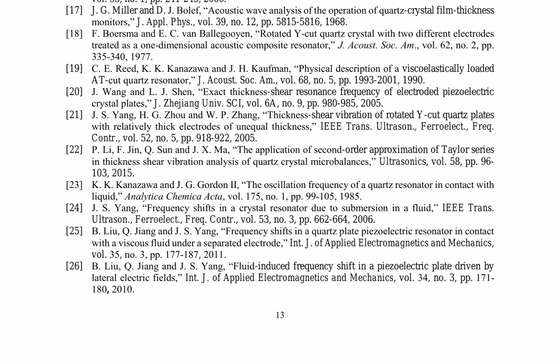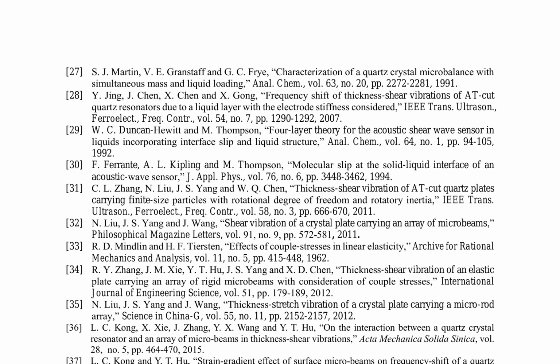It then explores the impact of these loadings on the frequency shifts of the quartz crystal resonators in thickness shear modes. The authors also delve into the effects of couple stresses and strain gradients on the vibrations of the piezoelectric plates, providing detailed mathematical models and equations to describe these phenomena. Furthermore, they examine the interactions between the quartz crystal resonator and an array of microbeams or hemispherical substance units immersed in a liquid, shedding light on how these interactions influence the frequency shifts of the resonator.